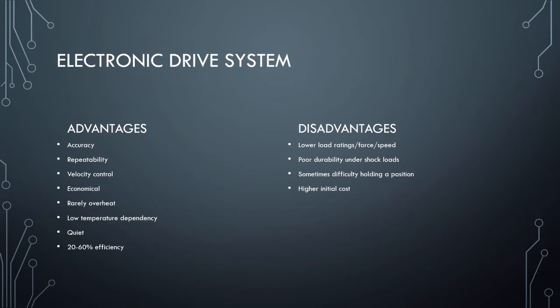Of course, like with any system, there's some drawbacks. So I alluded to this in the last slide when I was talking about hydraulic systems, but our electronic drive systems are for much lower loads. They can't exert large forces or move too fast.